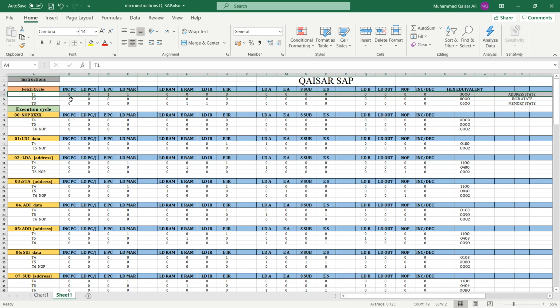I need the output signals from the two ROMs at T1, and similarly at T2 and T3, to have these specific combinations of signals. So I wrote this data to that ROM. What a ROM actually takes is the opcode from the instruction register.